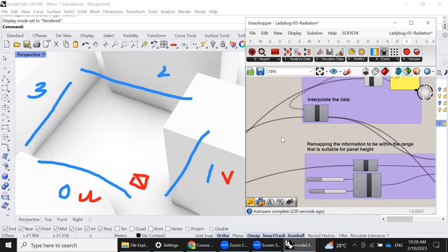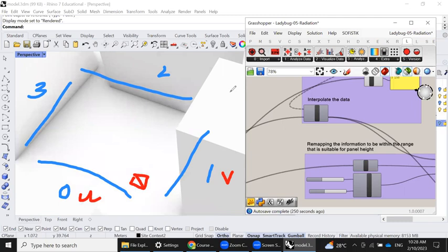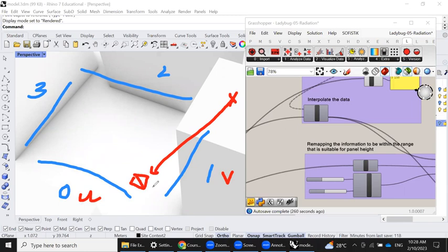So in the very first lesson of the Esplanade Sunshade, we shared with you how to use the amplitude as a slider to directly change the height of the Esplanade Sunshade. Then after that, we used an attractor point, remember? The attractor point will measure the distance from the point to your midpoint, and then use this as the height for the sunshade.